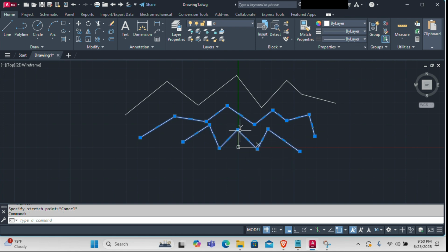So let's talk about arc segments, as you have now known the difference between polyline and line. Simply remember, this line structure is made up of many connected individual lines, but a polyline is a single connected line. It is one object. A line is one object, but you form this figure by using multiple lines. But a polyline is a single object.